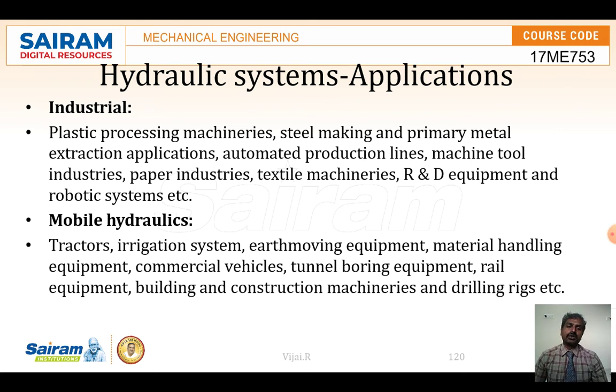Hydraulic systems are used in most industrial automated production lines for pick-and-place robots, moving material from one place to another, and punching operations. We can use them for extrusion, extension and pressing operations, and pumping lines also. In CNC machines or machine tool operations, the movement of pistons and slides can be controlled with the help of linear actuators.